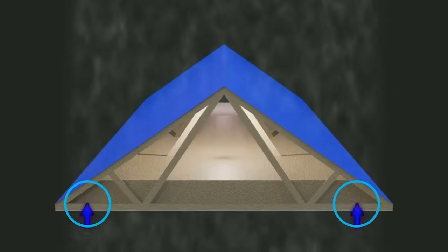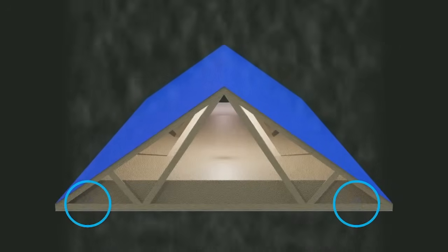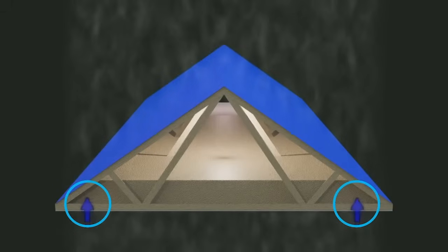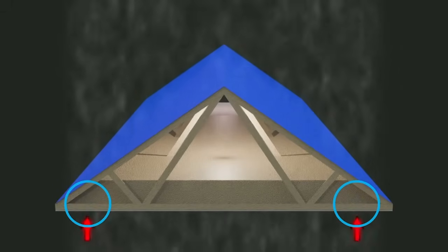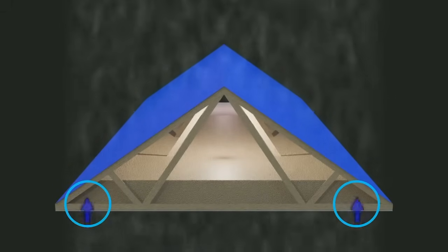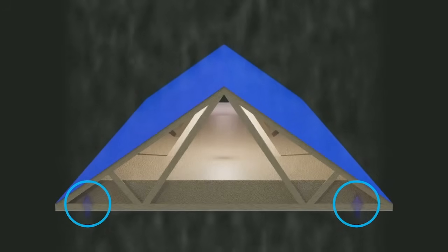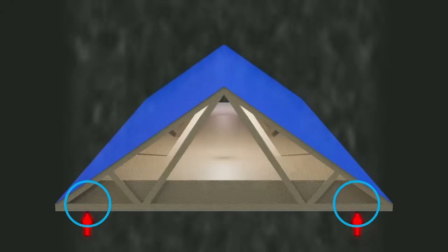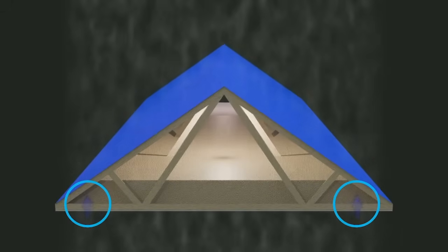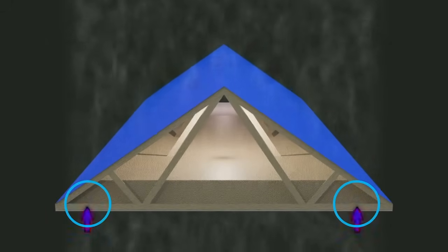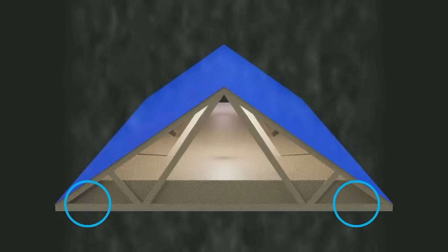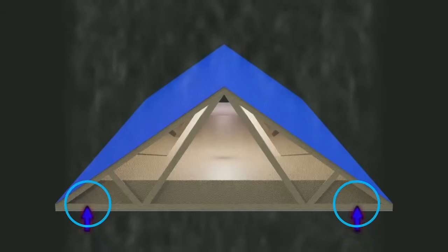Lastly, the latest 2023 amendments to Approved Document L require a significant increase in the depth of loft insulation, which makes the detailing of the eaves problematic. If the insulation does not extend a sufficient distance into the eaves, it can introduce a cold bridge at the junction with the walls. However, if it's pushed in too tightly, it can obstruct the openings for ventilation. This means additional measures such as plastic trays or ventilators must be used to ensure airflow is maintained.